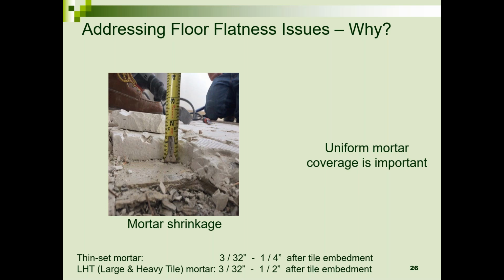And if you look at the lower left there, you'll see your typical thin set should be no thicker than 1/4 inch after you embed the tile. Your mortars that are specifically formulated for large and heavy, large format tiles, generally no greater than 1/2 inch after you embed the tile. So if you're trying to flatten the surface and adhere a tile, you're more than likely going to use too much mortar and you're going to have problems.